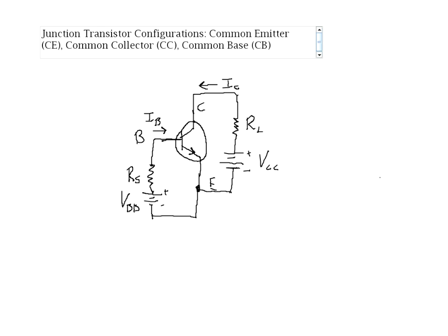If we want to know how this behaves, then we need to look at the current voltage curve. But since this is a three-terminal device, we need an entire series of current voltage curves in order to understand how it's going to work. So what's commonly done is plot what is called a set of characteristic curves for the configuration.